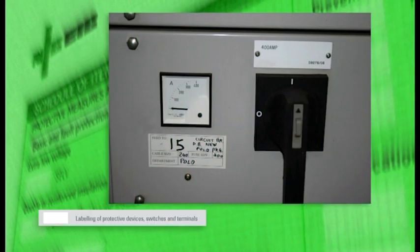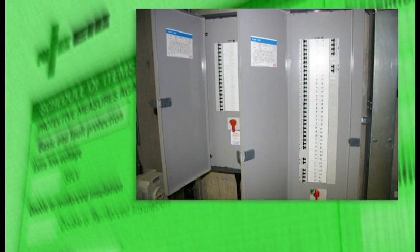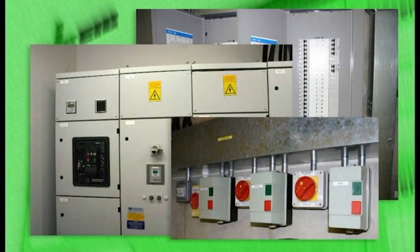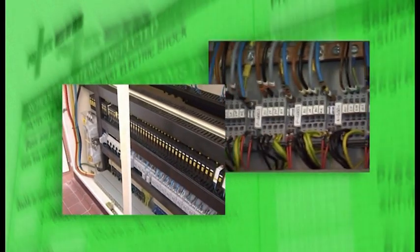Next, we have labelling of protective devices, switches and terminals. And here we're checking again that where required, identification is present. Except where there is no possibility of confusion, all switches and devices for controls should have a suitable means of identification to indicate its purpose and the installation or circuit it controls. For some complex installations, where the arrangement within equipment does not identify the wiring sufficiently well, it may be necessary to identify the terminations of the conductors using a number or a code.